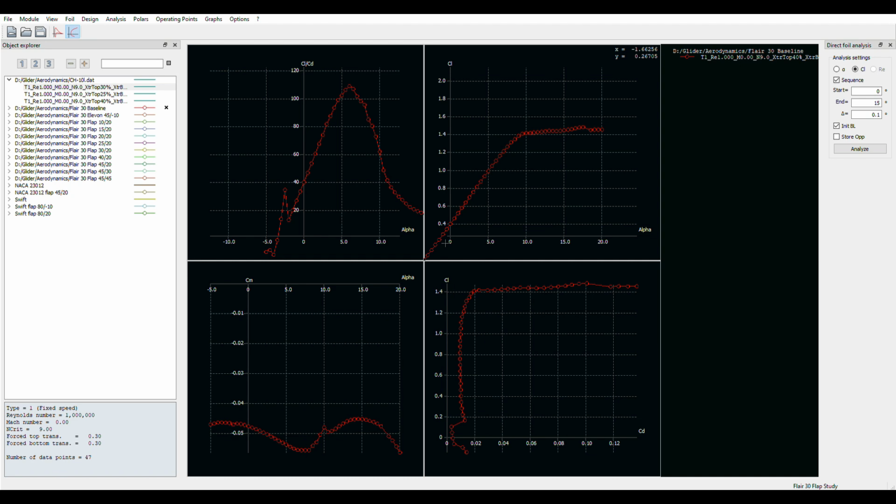It really should have had 10 degrees. It would probably have flown reasonably well at 8. 10 would have been better. The reason they kept the washout low is to reduce the drag and get better performance. But they created a wing that had handling issues to some extent. Okay, so that's the Flair 30 airfoil.